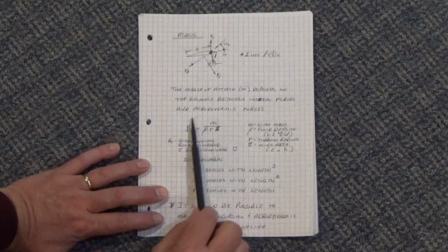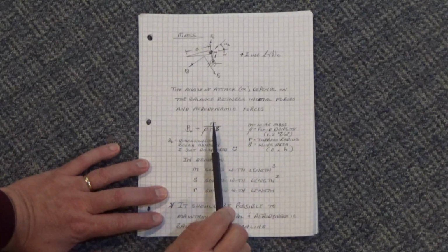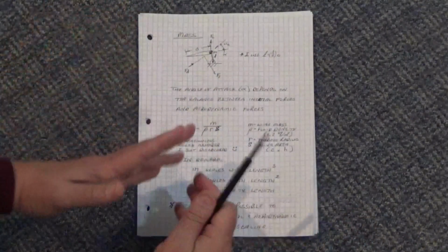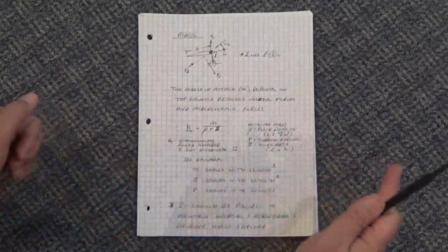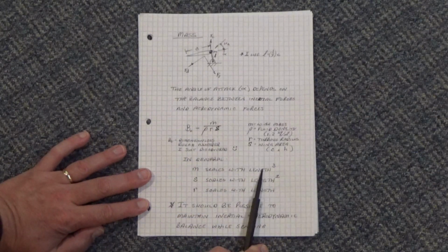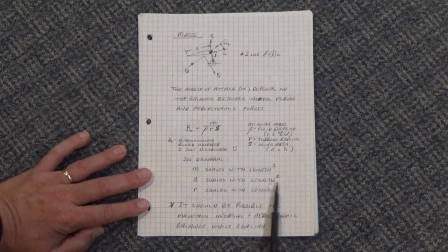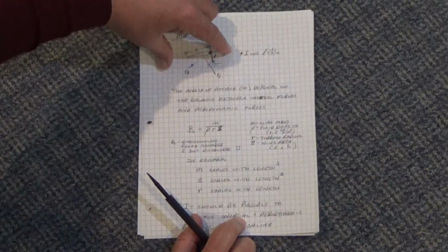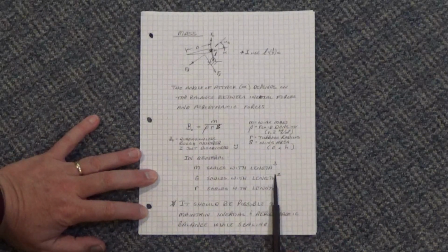So this turns out to be a dimensionless number, and in general, the mass will increase with the cube of the length. So if you double the size of something, you double the width and the height and the depth. And so the mass tends to go up with the cube of the length. And the area of the wing only goes up with the square of the length. So when you double the size of it, you only end up doubling the chord times the double height. So that's the length squared.